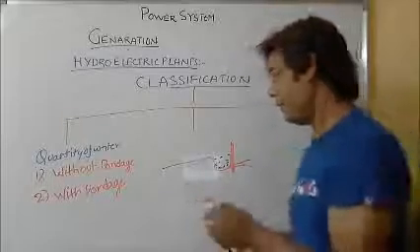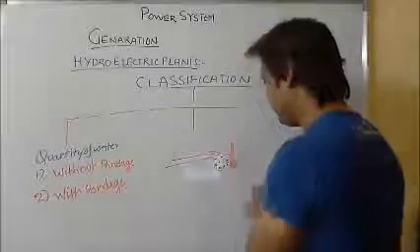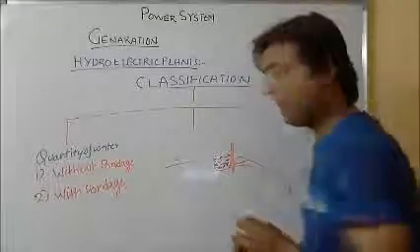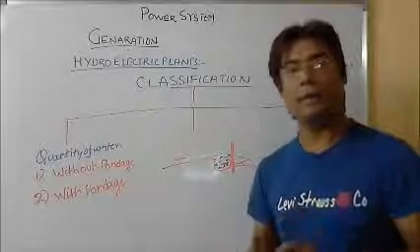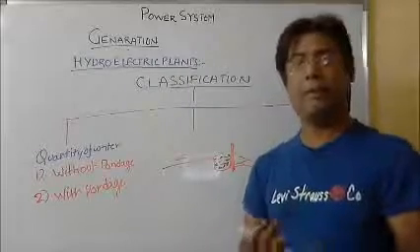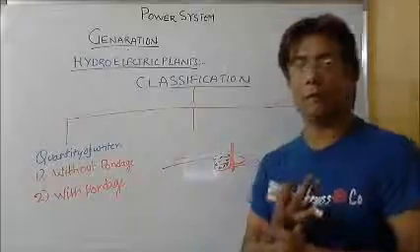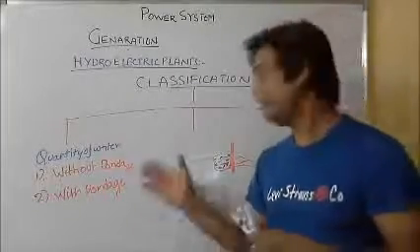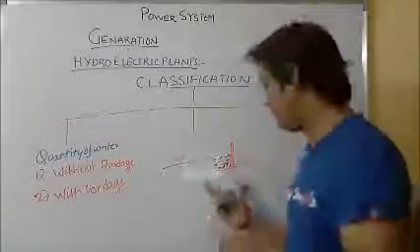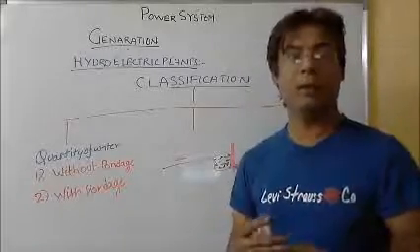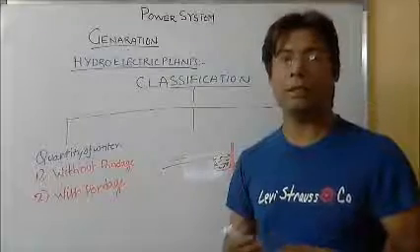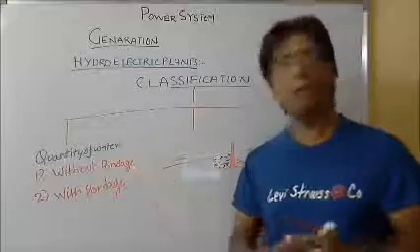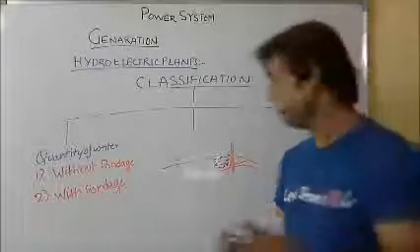When the water is normally coming, we are producing the electricity. When the water is not coming, we have some water so that we will be able to produce electricity whenever we are in requirement. So these plants are a little more reliable than those without pondage, but since the pond is very small, the reliability is not very high, though it is high in comparison to without pondage plants.